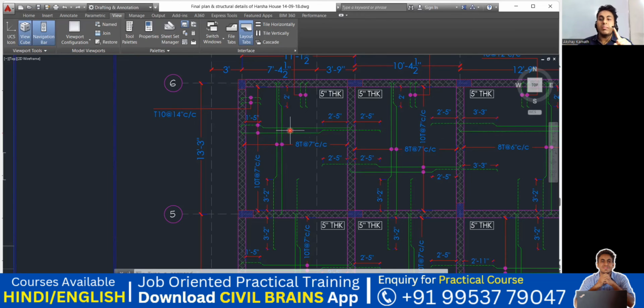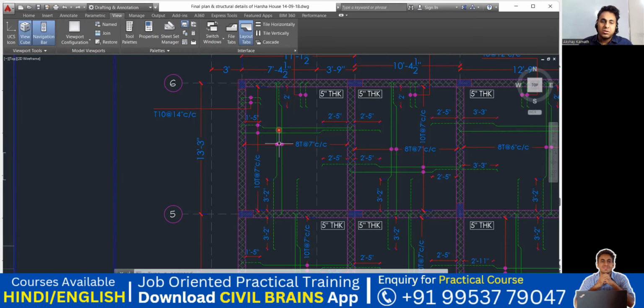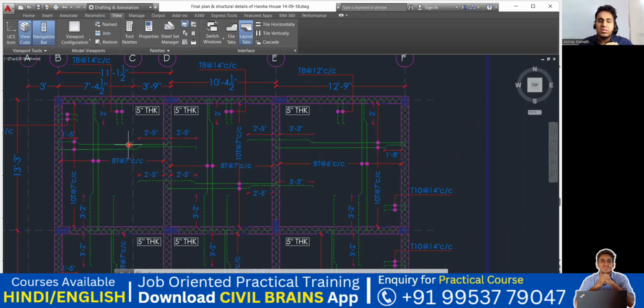So always the bars will be placed in the shorter span first, followed by the longer span. This is my shorter span and this is my longer span. In the shorter span, you're supposed to provide a 10 diameter bar at 7 inches center to center, and the longer direction will be your 8 diameter bar at 7 inches center to center spacing. Got it? Rest other things remain the same. It's very simple. Whatever I explained here, the same thing they have given here.